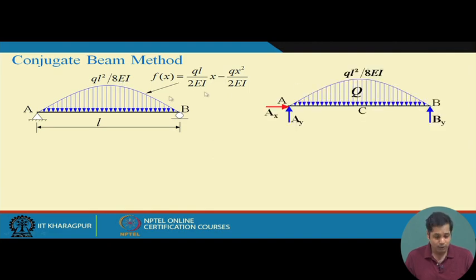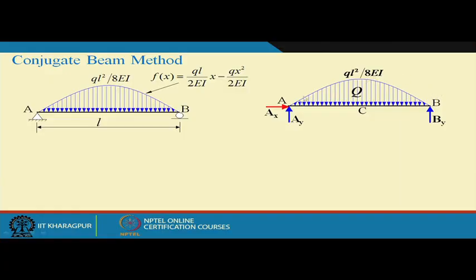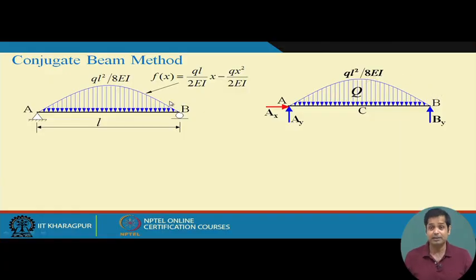Now, let us draw the free body. The only thing is we need to find the internal forces. So a problem of kinematics is now formulated as a problem of statics. Determination of internal forces is probably easier than finding deflection and slope in a structure.